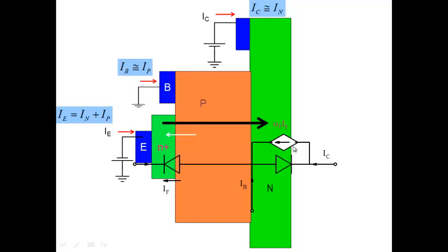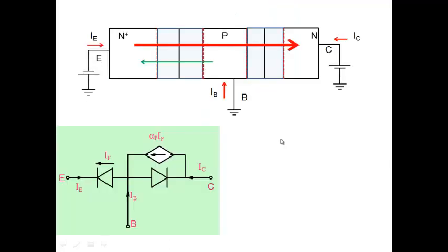So that's the key difference between a bipolar transistor and two diodes fused together. Two diodes simply connected together: if I take two diodes connected together, I'll get this and this, that's it. Now, because of this arrangement here, you get this current here. So this is the key current. This is where all the bipolar action is: you have a current injected at one junction, which flows into the other junction here. So the whole story is with this particular dependent current source, a current dependent current source here. Whatever current flows here, a part flows here. So that is the key part.